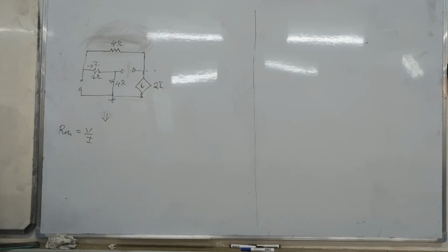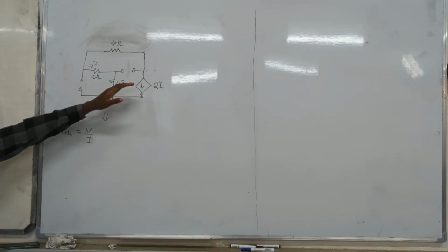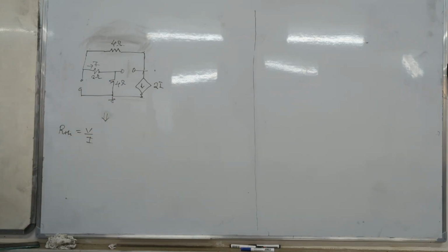That's what you are doing, even in the other one. But for the other one, you don't state those steps. Why? It has no dependent source. So when you switch off everything, all the sources are eliminated from the circuit. It becomes simpler. So doing that step would just make things complicated. But that's what you are doing.